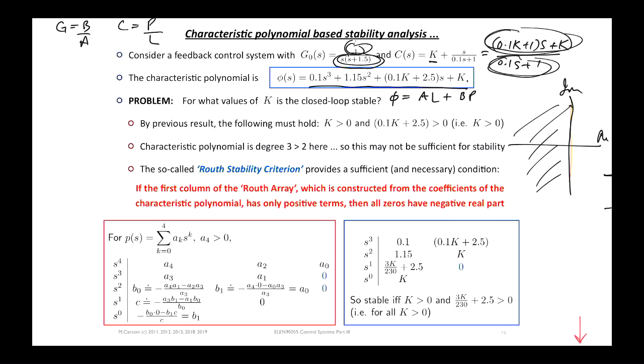This one, because that's the transfer function from R to Y. So if we apply the final value theorem to it, this transfer function times s, and take the limit as s goes to 0, we get 1. Is that what we should expect?